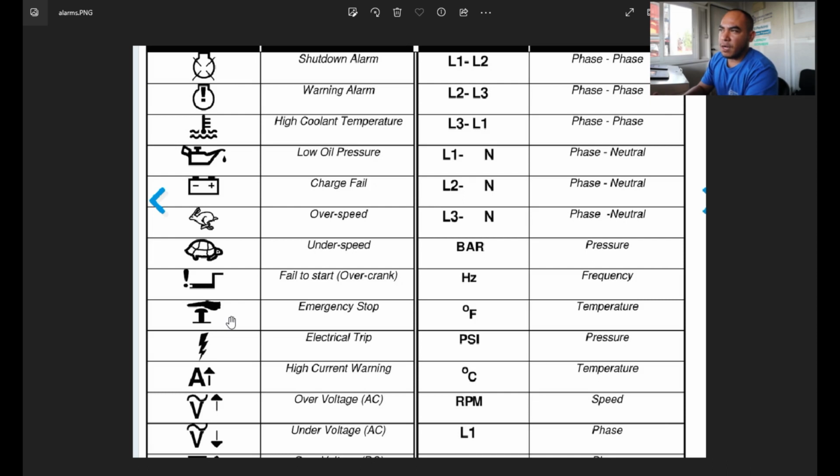Also, you have to look at the configurations, if the set points you configured are correct, because sometimes if you make a mistake, the emergency stop will pop up even if it is not pushed, or even if the wiring is connected properly, or even if the contact is correct. You have to look at the configurations too. So these are the things you have to look at if you are going to troubleshoot this kind of problem. First, the wiring.